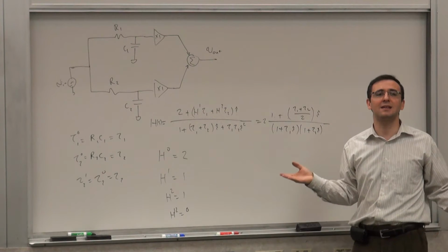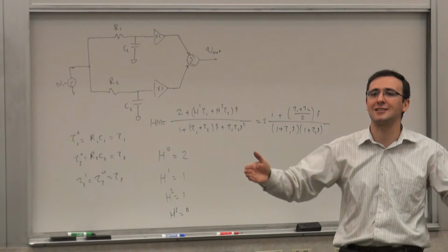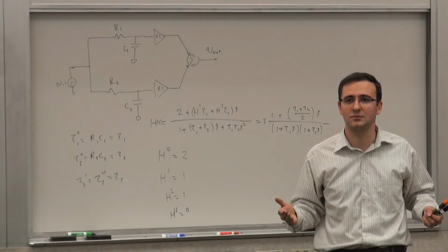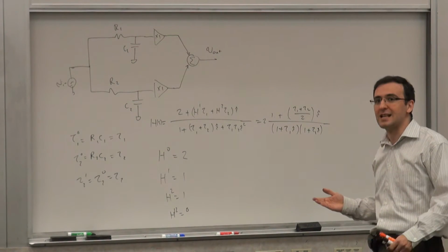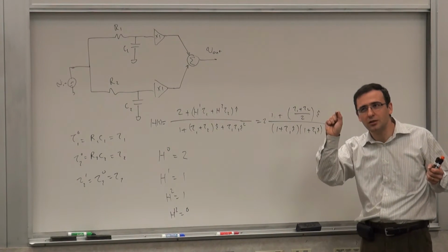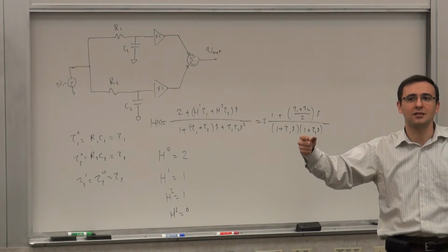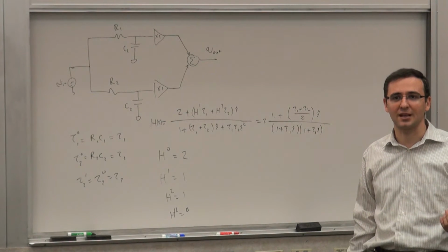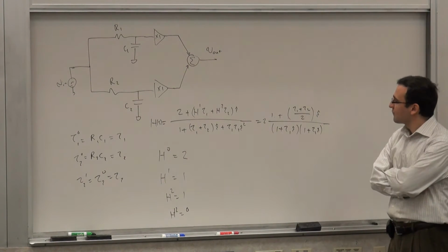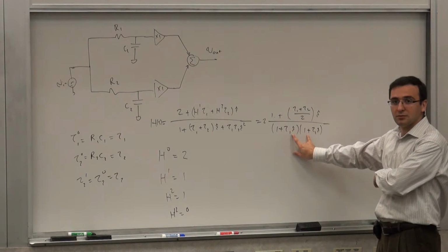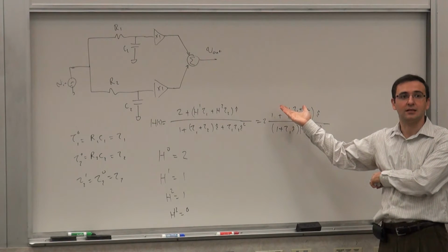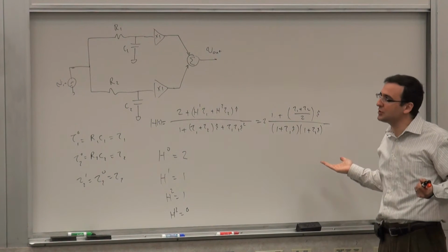This is actually one mechanism you can create 0. Anytime you have 2 parallel signal paths or multiple signal paths, you create zeros. And that's actually one of the telltales of when you create 0. You can look at it and say, well, do I have parallel signal paths? And I'll show you another example, a circuit example in a second. And you see, although the poles are decoupled, the 0 is created.